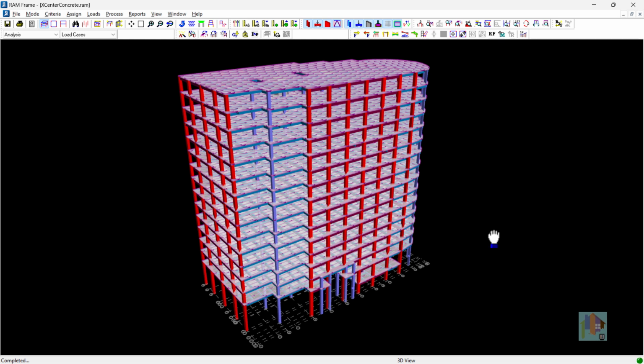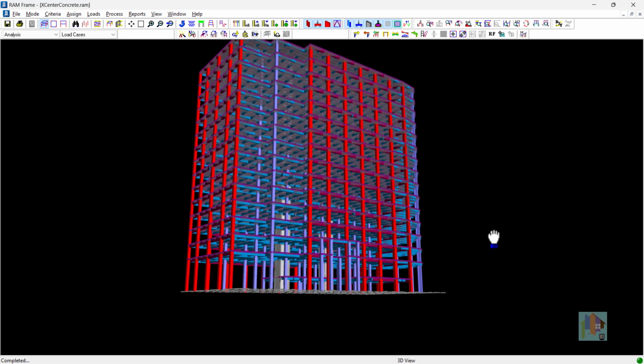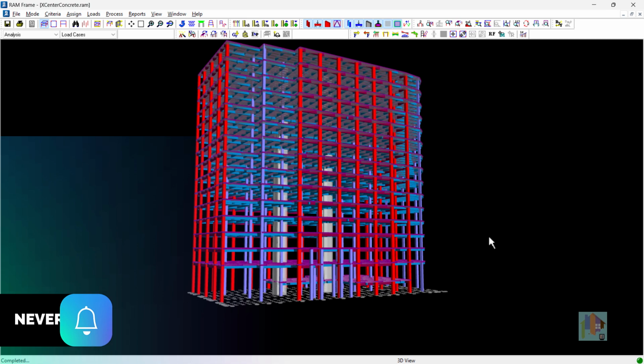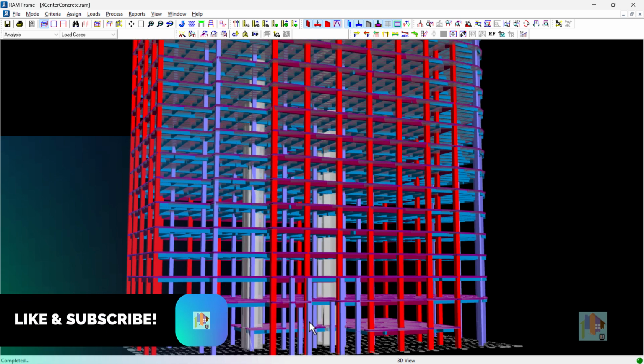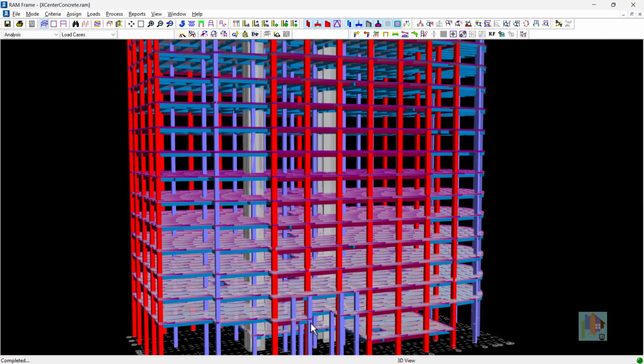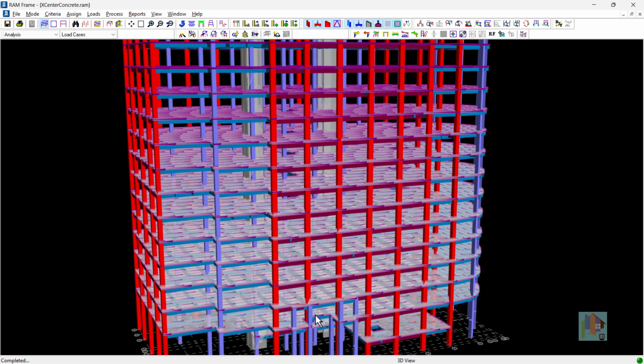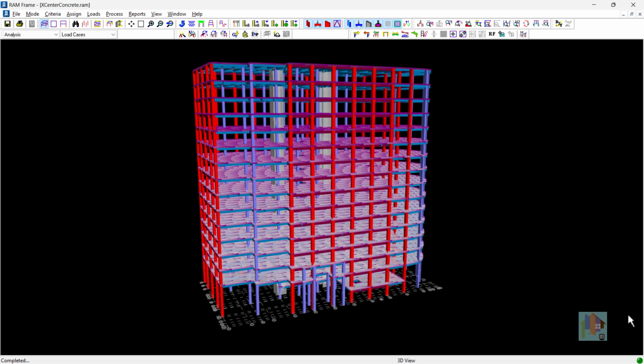It has a plaza level with dual height floor. The rest of the floors can be utilized for residential or commercial purpose. Structurally, it has a dual framing system with a shear core and rigid floor diaphragm modeled with finite element mesh. Different loads are applied on the structure, including gravity, lateral and construction stage load.